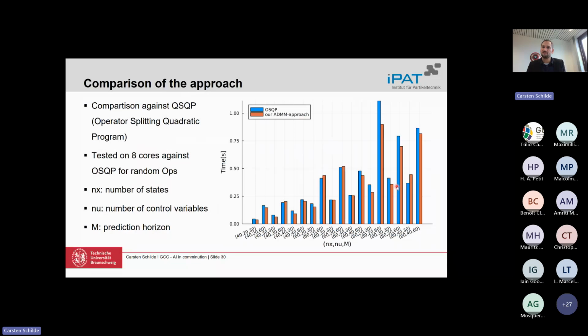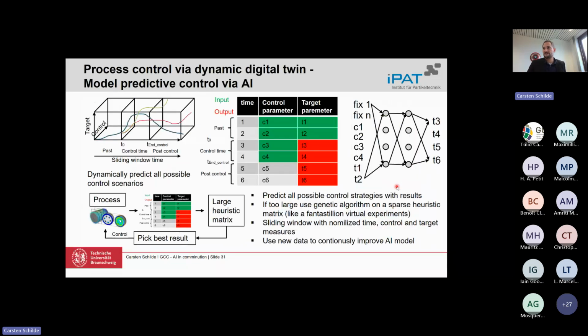But what you can also do is use the same strategy as given in the slides before, and here shown in the upper left of this slide, using not a physically inspired population balance model or the King's model. You can also just train an artificial neural network and make these predictions. And this is presented here on this slide, where we use a kind of neural controller.